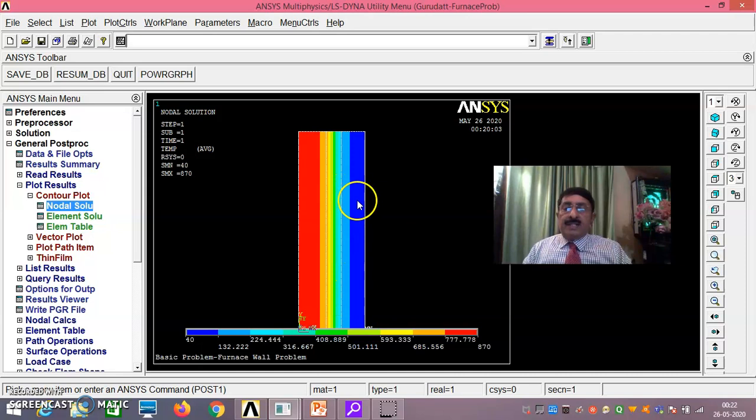Now these are basic things, anyway I can demonstrate once more. But before that, I'll apply the temperature gradient to show how it varies. Now it is 800 here. By the time it comes here, it should be 40. The thickness of the first layer is up to here, it is 0.135. Next is 0.075. And next is 0.115. Totally amounting to 0.325 meters.